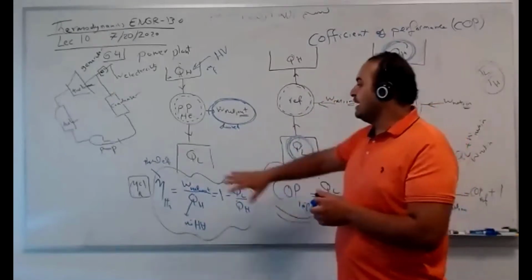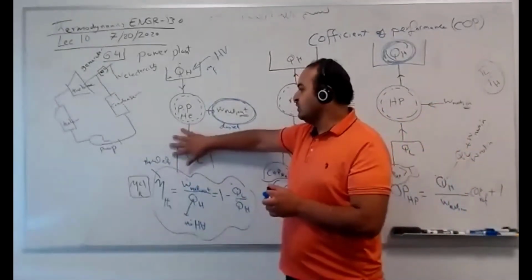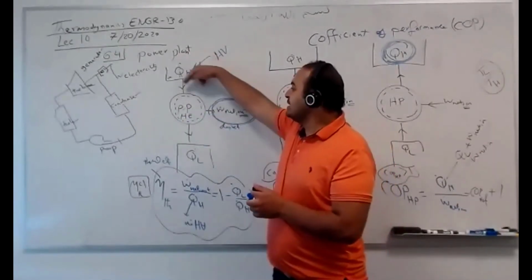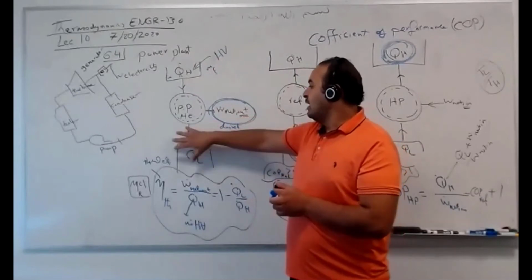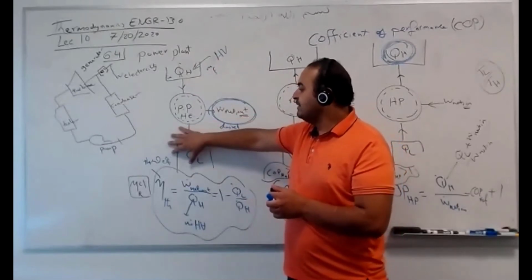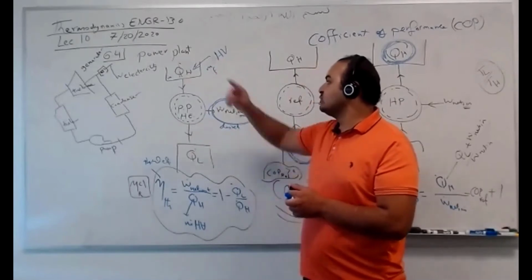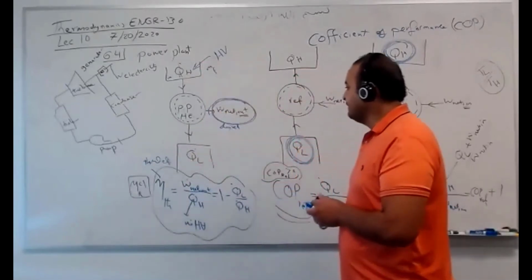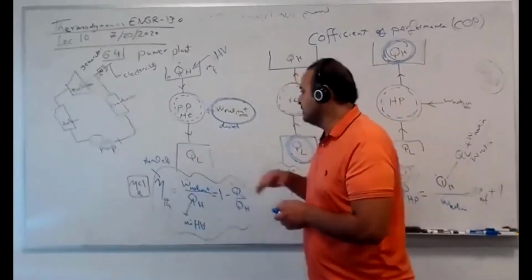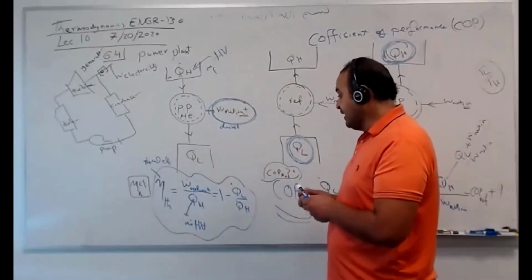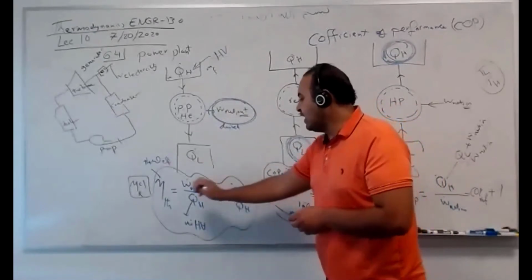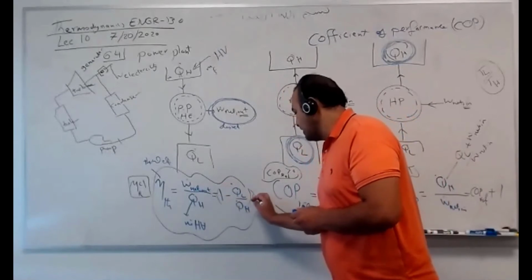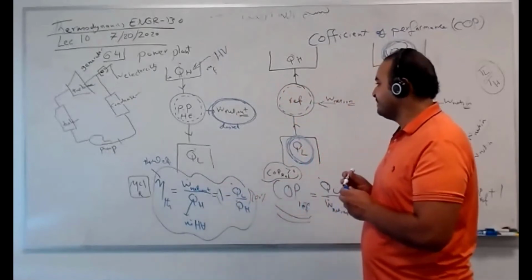Second law says you cannot have this. You need to have this. If you don't have it, you don't have a cycle. If you have a cycle that operates with one single reservoir, you cannot have net work. From where? Kelvin-Planck statement. So you always need two reservoirs, Q high and Q low. One source, one sink. Some of the energy is not useful. But if Q low is 0, which is impossible, you have 100% efficiency. Of course, if you want percentage, you can multiply by 100%.